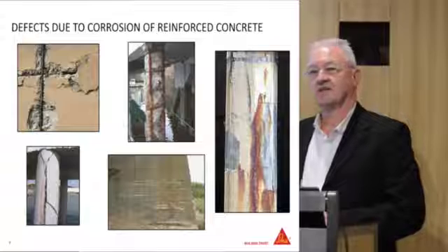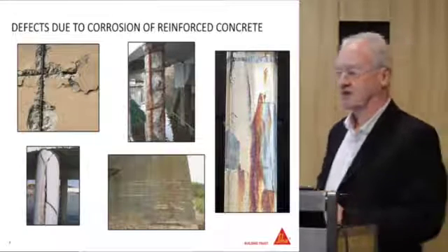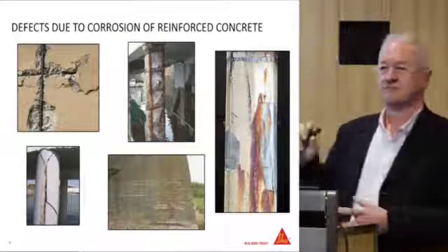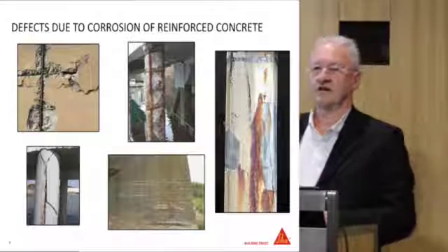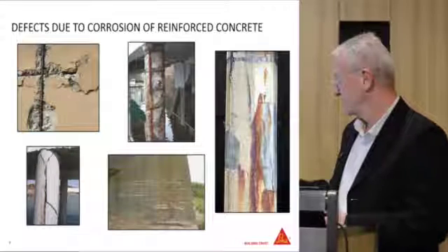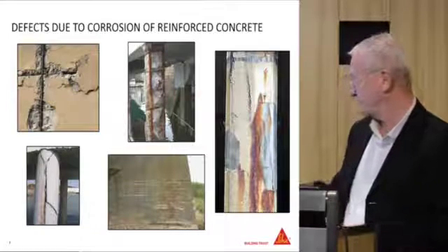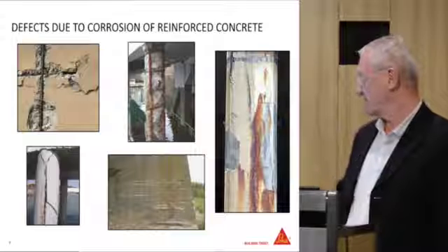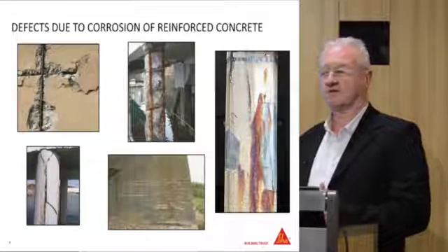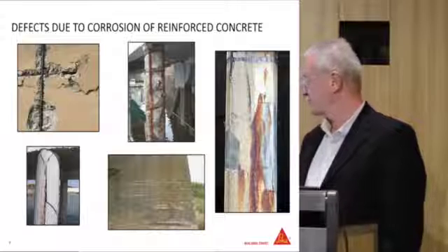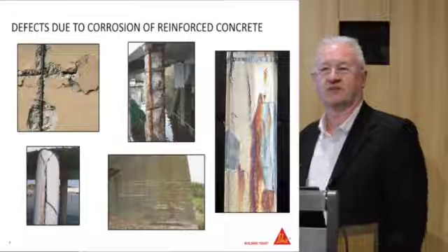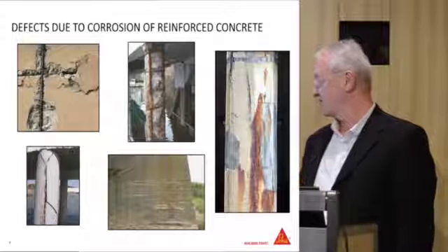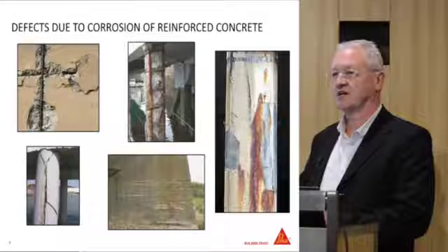This is something I'll cover in a little bit more detail in a moment, but Chris was talking about repairs, how they were carried out many years ago, where you just cut out the defective concrete, do something to the steel, put repair material in, leave it, and walk away, and hopefully everything works well. Well, this proves it really doesn't. You can see a repair there, and everything around it has started to corrode. That, which was originally anodic, corroding away quite nicely, and the big cathode, which was the rest of the reinforcement in there, was driving that process. Then what's happened now is that this has become the cathode, and that's driving the corrosion now, which is occurring and bubbling under the concrete cover.